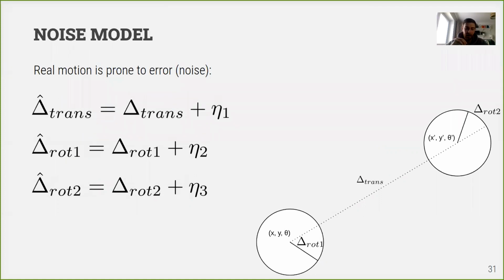So basically we had many hypotheses on our pose, and we were moving them separately, generating different noise for different particles. And this is exactly this step. So for each particle, we are performing this prediction many times. For example, we have 100 particles.